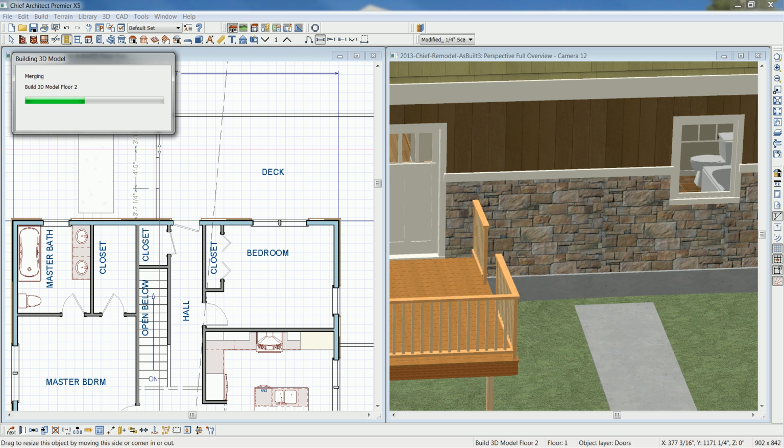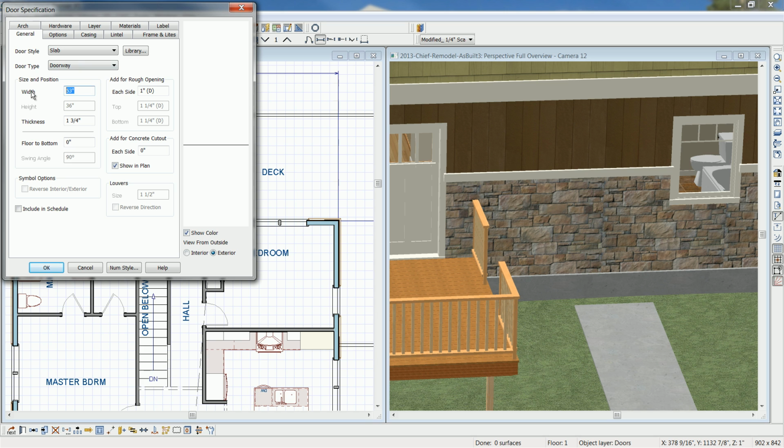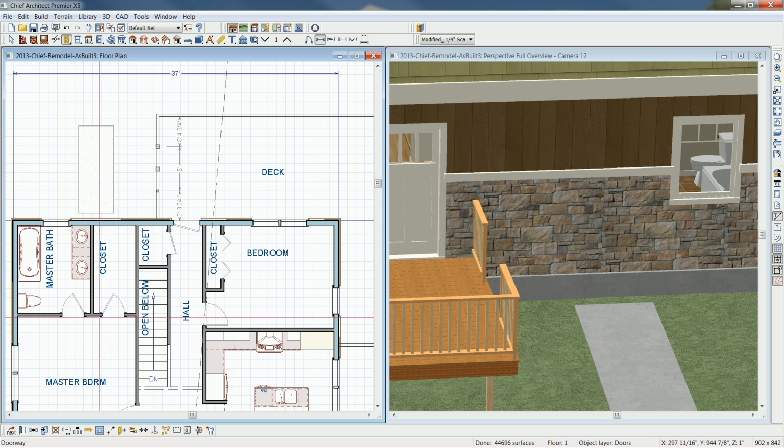And depending on the width of the railing, let's go ahead and, if you want that to be exactly 5 feet, you can open that up. You can either type in inches or feet in the dialogs. We'll set that to be 5 feet. And again, if you want to use your center tool, that will exactly center that opening in that room.